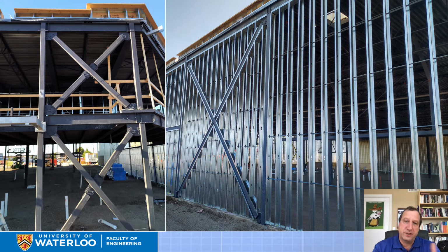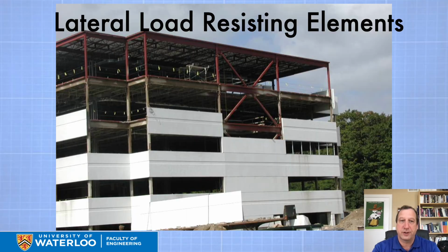And so we see an X-brace in both, and you can also get a closer look at the kind of connections. These braces seem to be taking a lot more load, and it is common today to make those heavier loaded braces out of hollow structural tube. Lighter weight braces often are made out of angle steel and occasionally out of rod, solid rod, but heavier loads tend to be into HSSs. They're very efficient systems for that, the steel efficient system.